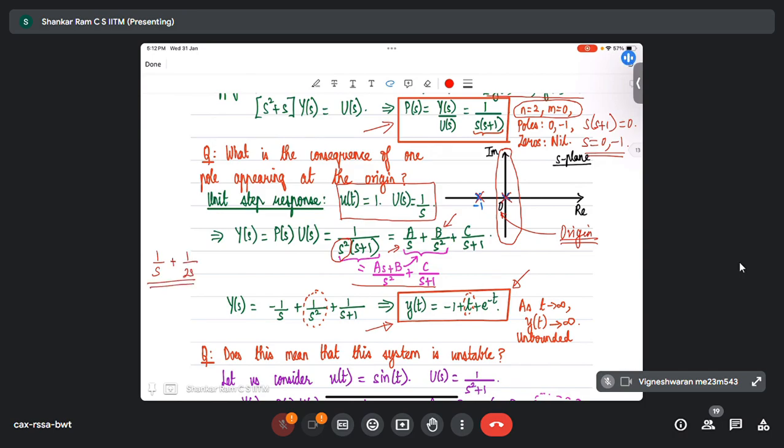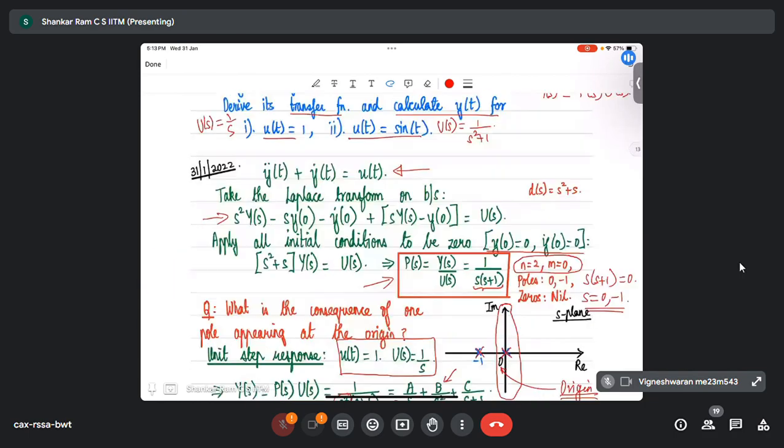I think you can add them and take the inverse Laplace transform, because please note, Laplace and inverse are both linear operators. Doesn't matter whether you do it individually or you add and take it. But if suppose it is coming from the input response and from the free response, in that case, should we do it separately, or can that also be added? So if you want to segregate them for our own understanding to begin with, saying this is the free response, this is the forced response, I can see where you are coming from, right?